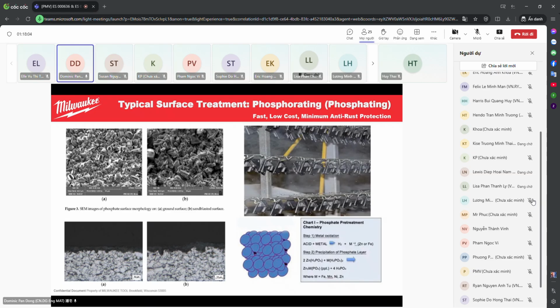So the anti-wearing performance is not that good. And also because of those porosities existing on the surface of the phosphating parts, usually we would add dipping inside anti-rust oil to get a sealing effect on the surface gaps so that we can get a very stable anti-corrosion performance under salt spray testing.